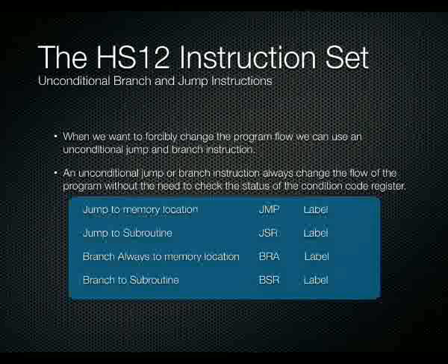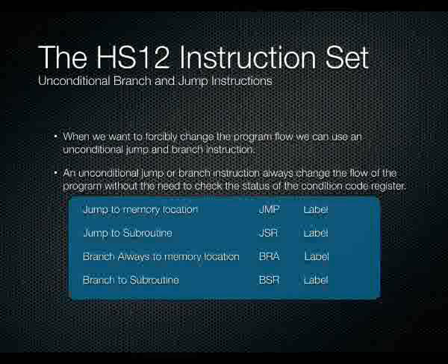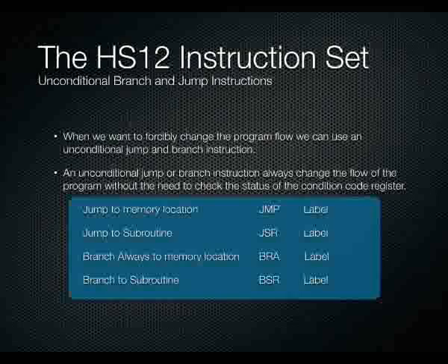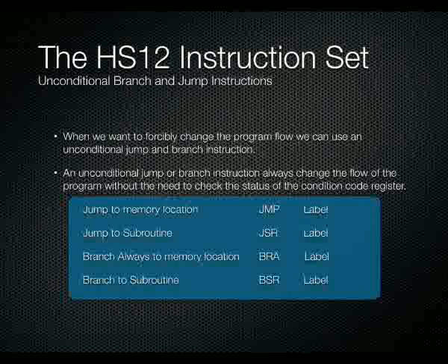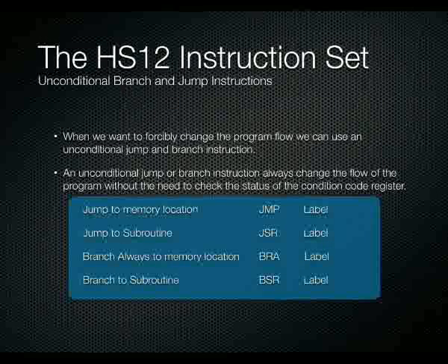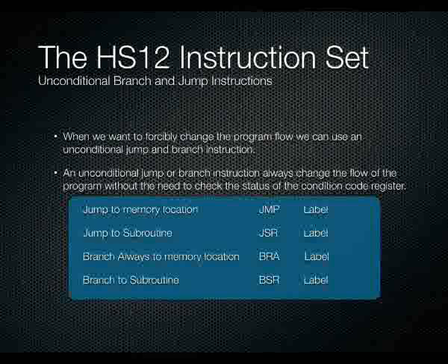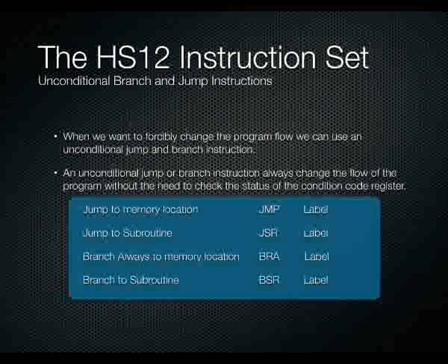One thing to keep in mind with the jump to subroutine and the branch to subroutine is that when you run those commands, it effectively pushes a return value onto the stack. It'll push a 16-bit return value, the current program counter value, onto the stack. It'll then set the program counter to wherever you want it to go. In the case of JSR, it loads the operand into the program counter and then starts running that subroutine.